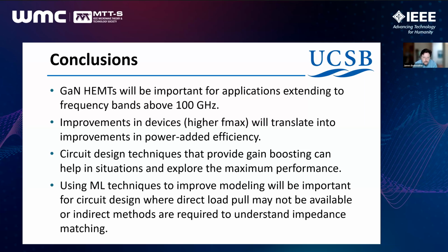And then finally, we introduced some ML techniques that we were looking at for using in our circuit design when we didn't have direct load pull. We had load pull, for instance, at 94 gigahertz, and we wanted to extract models at slightly higher frequencies.